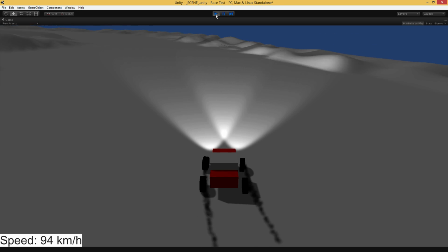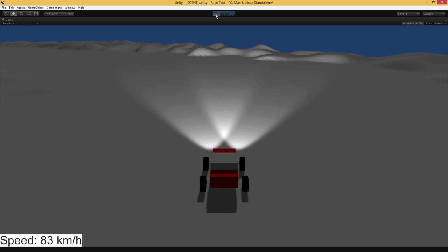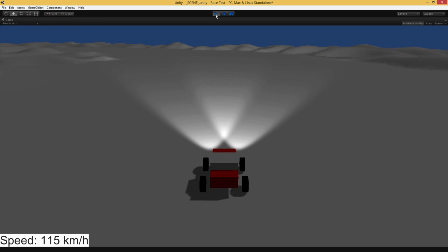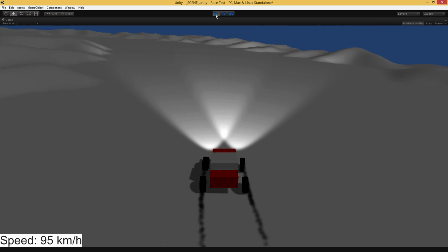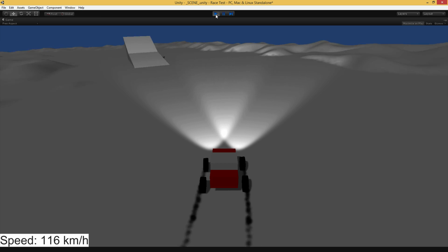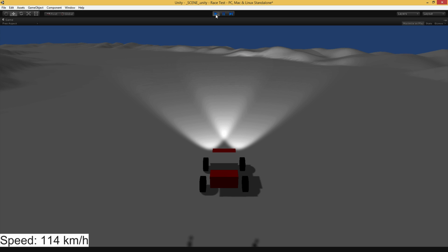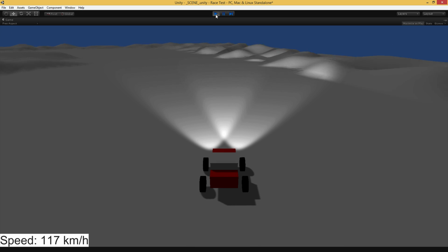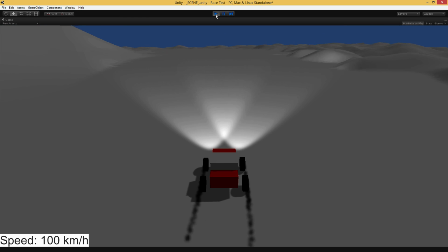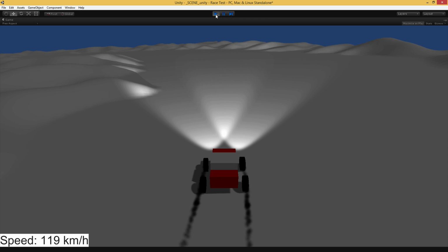And the reason real cars don't do it as much, partially it's the weight, and partially it's better suspension setup, which we'll have to talk about here. But real cars actually have anti-roll bars, which effectively transfer force from one side of the car to the other to try to counter these rolls. And really advanced cars with super computerized suspension, the computers will be calculating these forces. So an anti-roll bar is an actual mechanical thing, and in electronic computer-controlled situations, your computer can adjust your suspension settings on both sides to stiffen and weaken suspensions in response to a roll to cancel out rolls and things like that.